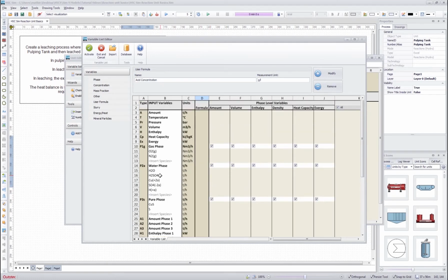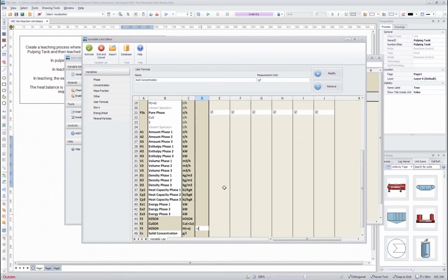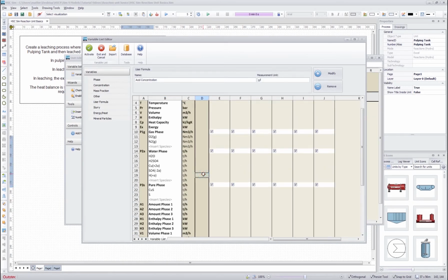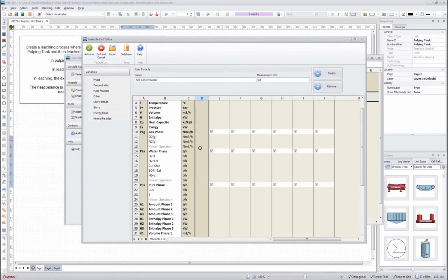And we want to take into account the effect of these, so we start by calculating the amounts of the hydrogen ion and sulfuric acid, and we divide by molar weight. And as everywhere else in HSC Sim, in all the Excels you can use these Excel calculation formulas that come with the sim, such as molar weight in this case, and then we have to divide it by 2 and then sum the hydrogen,